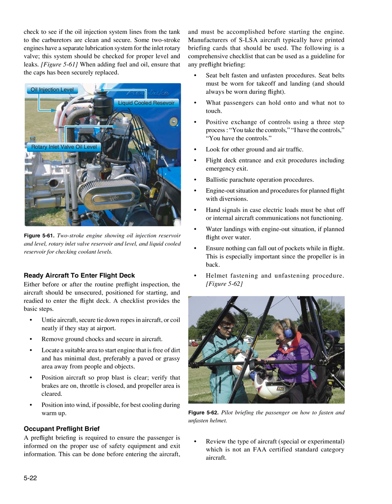Occupant pre-flight briefing is required to ensure the passenger is informed on the proper use of safety equipment and exit information. This can be done before entering the aircraft, and must be accomplished before starting the engine. Manufacturers of SLSA aircraft typically have printed briefing cards that should be used. The following is a comprehensive checklist that can be used as a guideline for any pre-flight briefing.